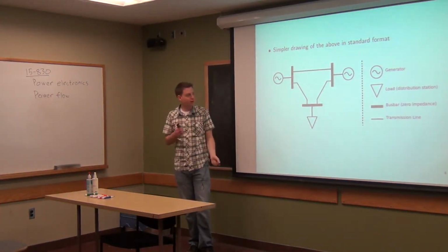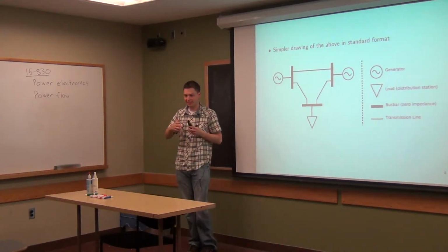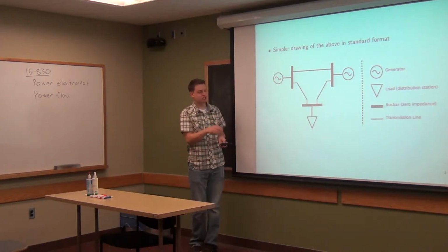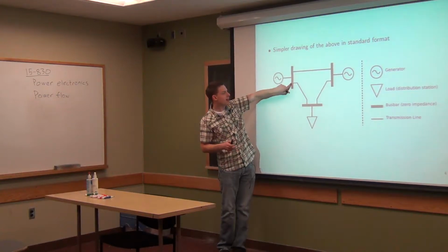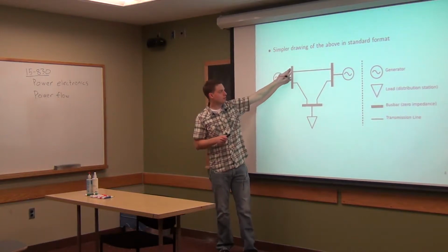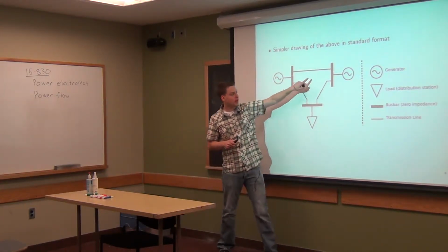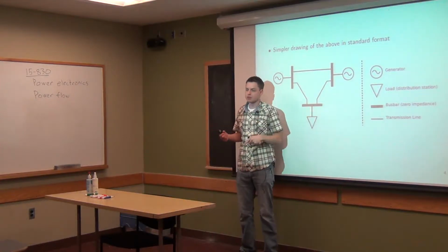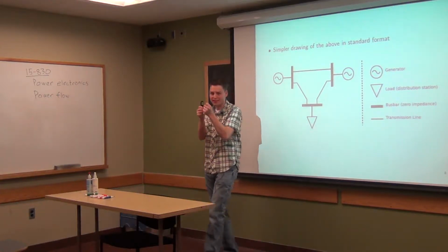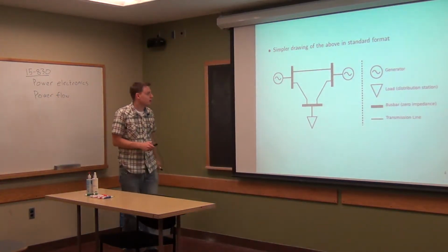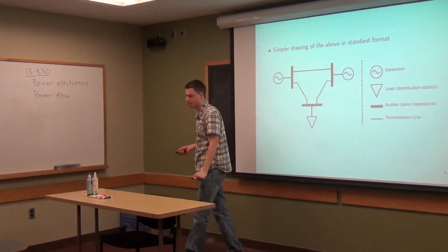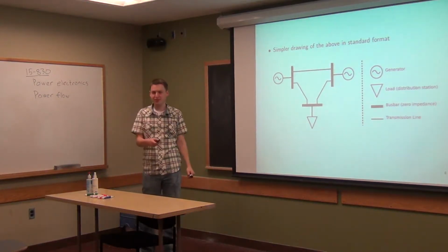I guess the term bus bar comes from the generators being connected to a big metal bus at their output. It sort of fixes their voltage. But really in diagrams, this just means that all the things connected to it are at the same point. You might have both generators and loads on one bus bar; we'll get to that later. You can assume these are like lines, but with zero resistance and zero impedance, so everything connected there is on the exact same point in the circuit. And then the lines are transmission lines, assumed to have some resistance and reactance, for a total impedance.